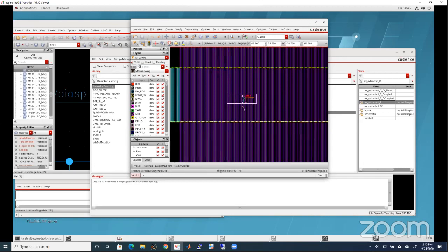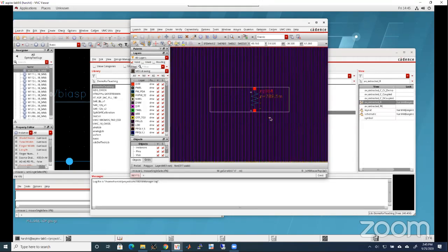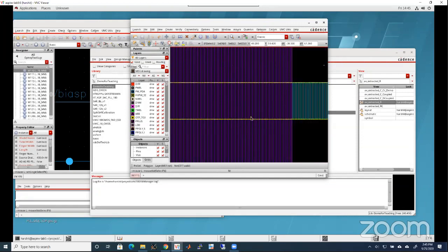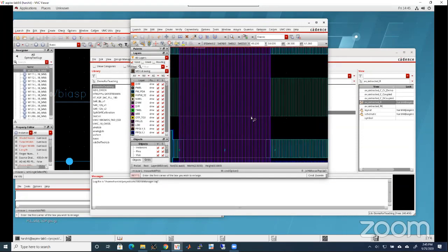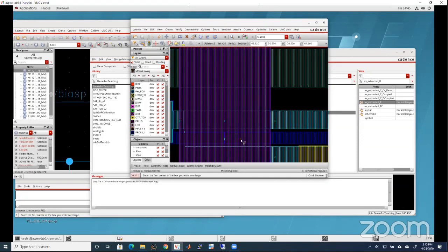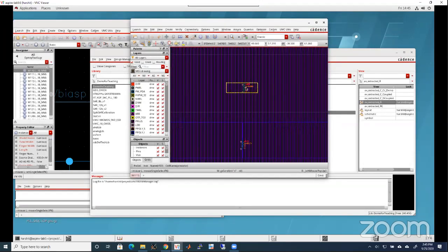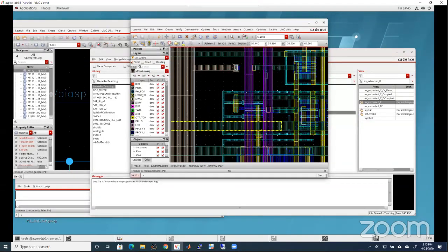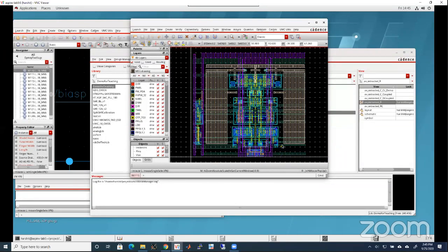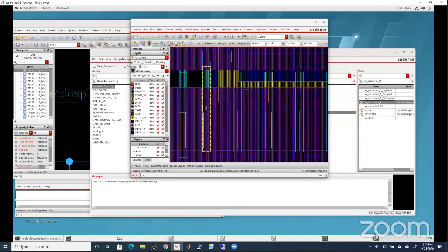You see a resistor here? A 789 milliohm resistor is there. So it will have the layout and it will put in the connections based on resistors. You see these resistors? These are all extracted resistors. And of course, it will put the transistor wherever there is a transistor also. For example, here there is a transistor. So let's zoom in and find out where the transistor is.